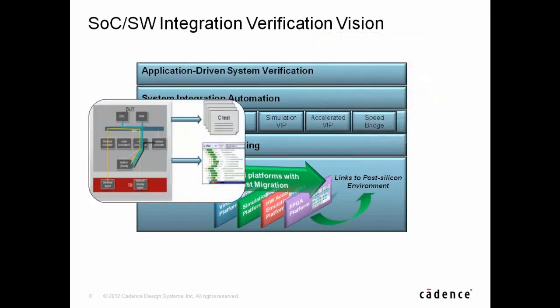And then we've had a product for a long time. So I think from about 2004, 2005, we had something called the Incisive Software Extensions. This allows you to basically connect a UVM test bench to your embedded software and randomize it, so you can get corner case scenarios created by randomizing the software. We've had this from about 2005. This is going to be extended further to address some of the use case scenario generation that you need for these things.